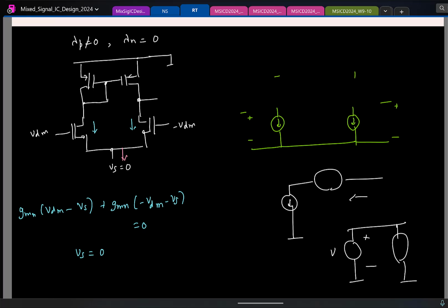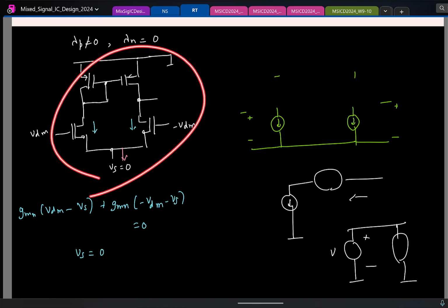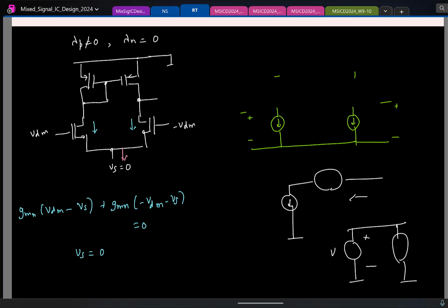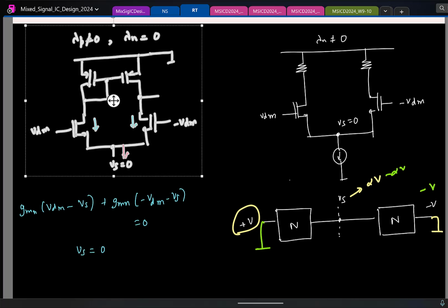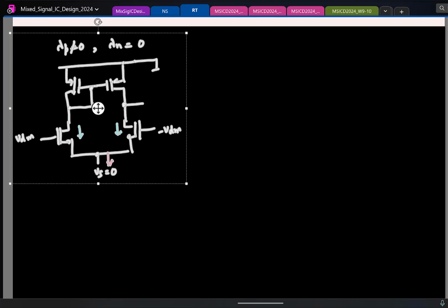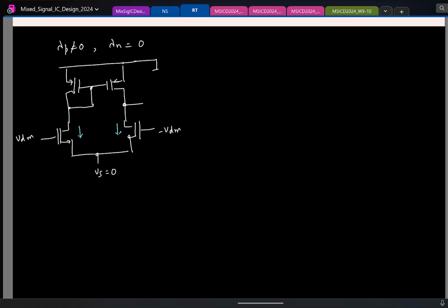So it's a nice interview question. You can ask, is there any condition by which this asymmetrical circuit can be thought of as symmetrical? And this is one scenario where this can happen. Cool. So is this point clear? So now let's get back to the calculation. Copy this. Yeah, so now I know the tail node voltage is incrementally 0. So what is the small signal current I1?